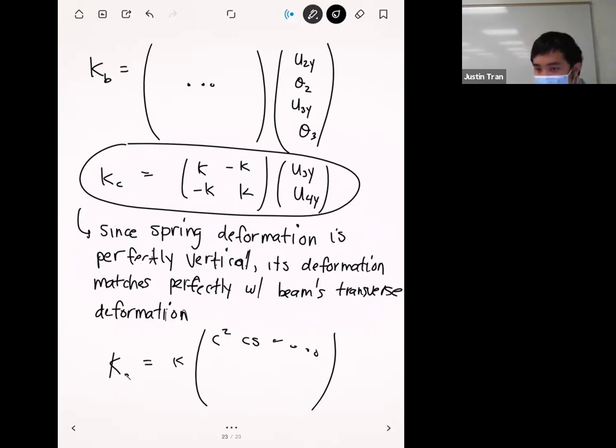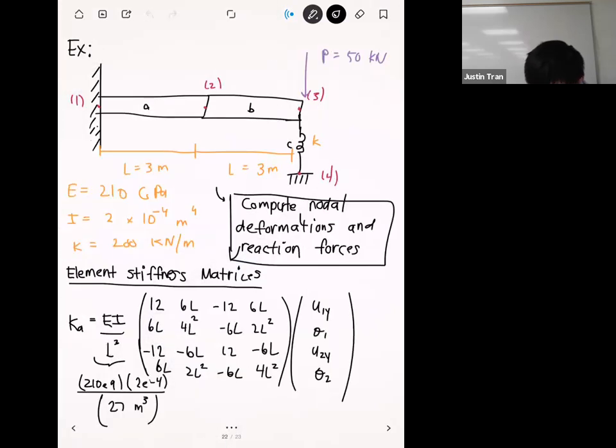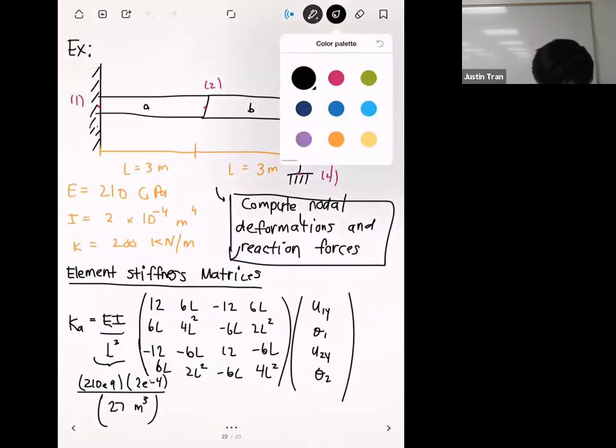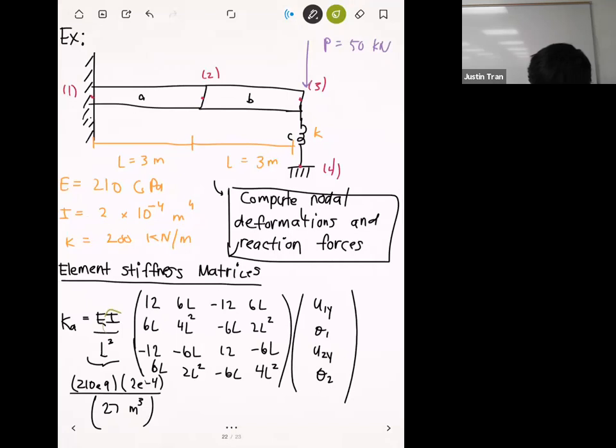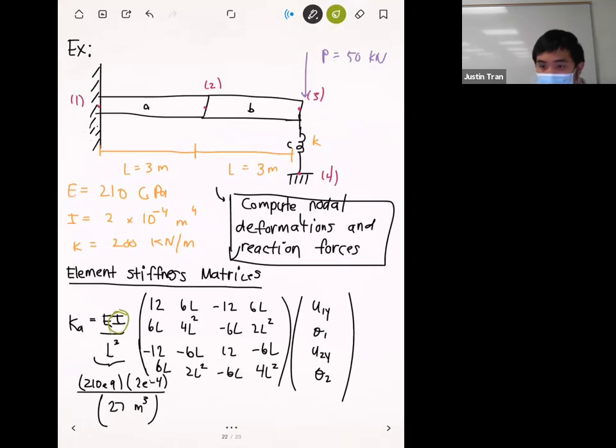And so the effect of the shape of the cross section, whether it be I beams, L beams, angle beams, that's going to be reflected in I. It's not a perfect representation because it's definitely possible for two beams of different cross-sectional shapes to have the same moment of inertia, but it at least gives you a pretty good first approximation.